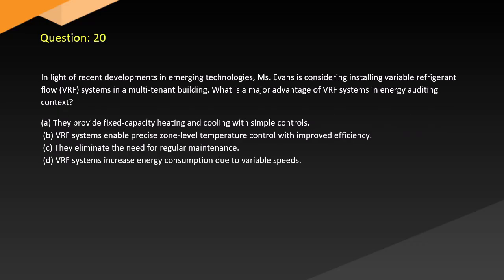Question 20. In light of recent developments in emerging technologies, Evans is considering installing variable refrigerant flow (VRF) systems in a multi-tenant building. What is a major advantage of VRF systems in an energy auditing context? A. They provide fixed capacity heating and cooling with simple controls. B. VRF systems enable precise zone level temperature control with improved efficiency. C. They eliminate the need for regular maintenance. D. VRF systems increase energy consumption due to variable speeds.